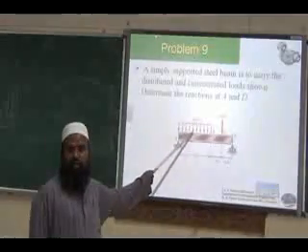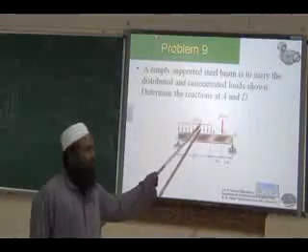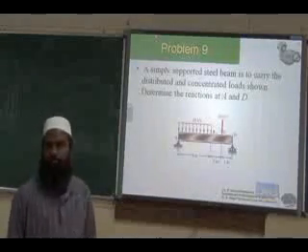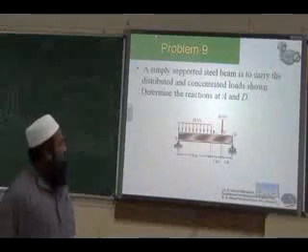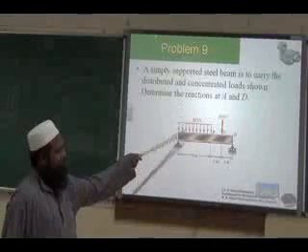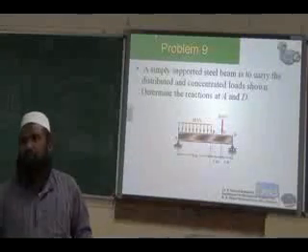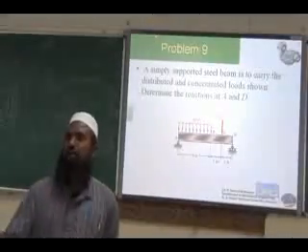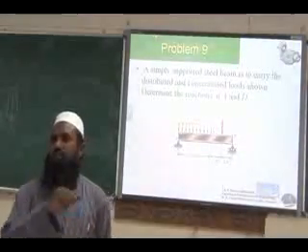The unit is kilonewtons per meter, and you have to convert it into a point load. After converting into a point load, you have to show the reactions.